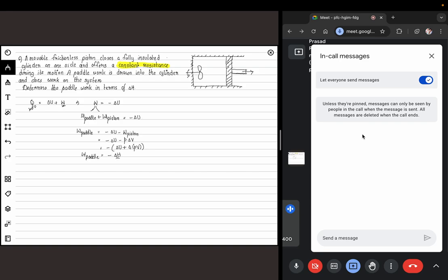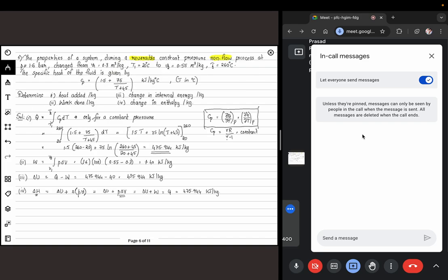Delta H in this case, since temperature is increasing, delta U will be positive, and accordingly the volume is also increasing, so both these terms are going to be positive. So delta H is positive, so work done by the paddle is going to be negative. Essentially you can say it directly even without this analysis, because as the wheel is rotating, you are externally supplying the work, so work is done on the system, so you are getting a negative value, which is also consistent with whatever we expected. So again, it's a constant pressure process. In the constant pressure process, any external work that you are doing will be equal to the change in enthalpy. So in the previous problem, when we discussed, your change in enthalpy is equal to your net heat transfer.